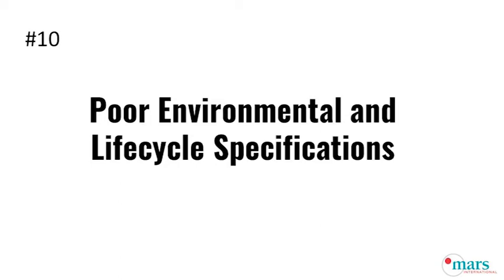In terms of life cycle specifications, that's the lifetime of the part. How long is the product supposed to last? We usually try to express that in terms of the number of operations. How many times can you push this button? How many times is this garage door supposed to open and close? Sometimes it can be a little challenging to figure out what that is, but usually you can get some rough order of magnitudes for what that should be over the use of your product, how many times per day you're expecting people to use it, and so on, and then giving yourself an adequate safety margin beyond that.